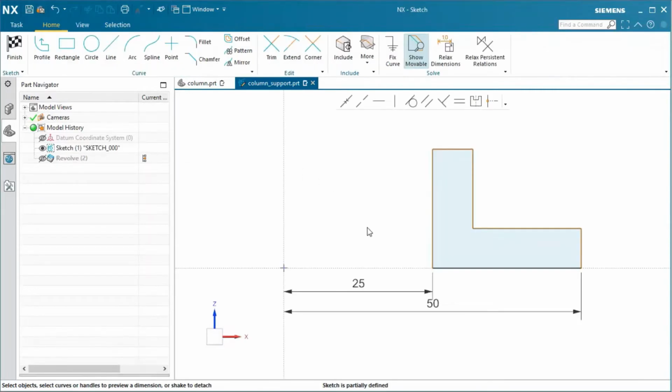The curve colors tell you that the bottom curve is fixed, while all others are still movable. When I select the outside curve, Sketch finds the curve ends and creates a preview dimension, which I'll set to 6 mm. Sketch axes are available for dimensioning. Picking the horizontal axis on the top curve gives me a height dimension, which I'll set to 25 mm.